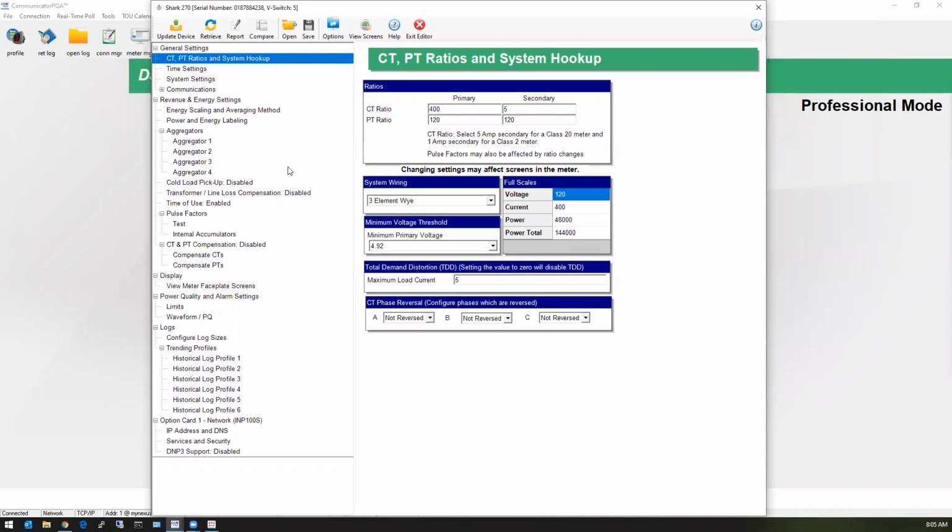Therefore, for example, if you have 20 amps per phase, your reverse polarity would read as a negative 20 amps on one particular phase. When you go to add your totals, you would get a total of 20 amps of load or generation, which would be incorrect. You should have a total of 60. So here we allow that software correction. It's always better to have a physical, actual installation that is correct, but in case you cannot access your gear, this is an alternative.